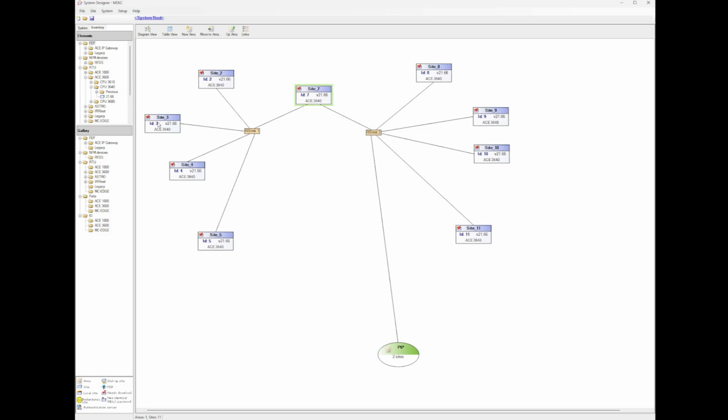In the same way, the same network table that's in site 7 will be in site 3, because site 3 will need to know where the RS link 2 is. So if we ask site 4 to communicate with site 11 and it doesn't know where RS link 2 is, then we've got an issue. It'll create a problem at the local RTU that's trying to send the data to site 11, and the communication will basically fail. It'll say, I cannot find that link ID in my configuration, I fail it, and we'll generate an error.